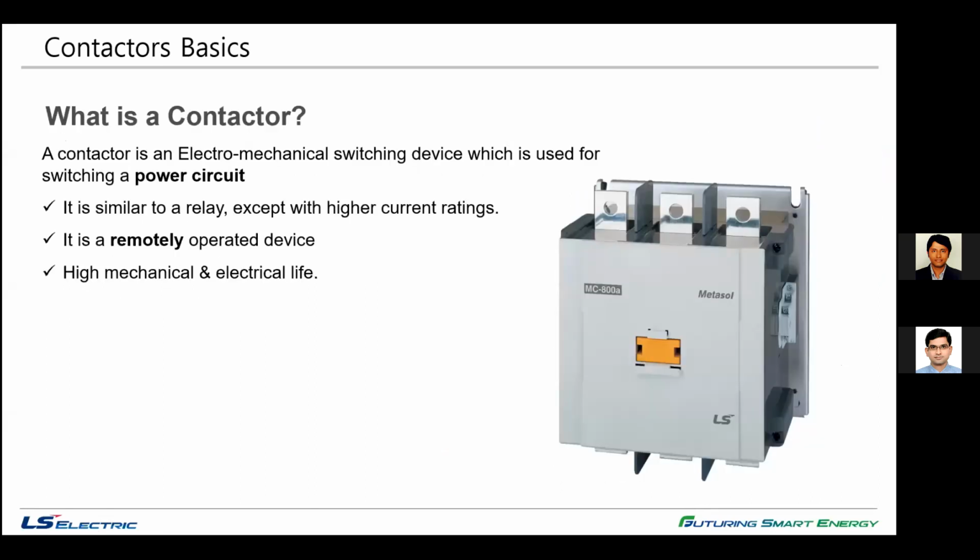The first question: what is a contactor? A contactor is an electromechanical switching device which is used for the switching of a power circuit. It is a remotely operable device. Contactors are used from the light switch to the most complex industrial machines, frequently switching on and off, opening and closing, making and breaking the circuits. It is used in lighting, motor, heater, and transformer circuits.